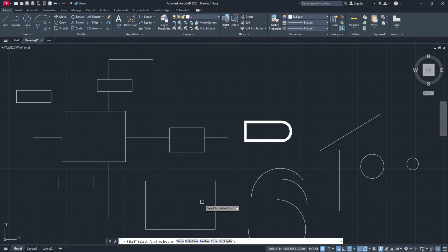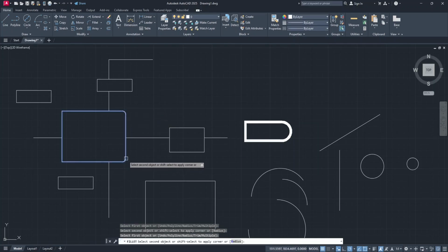As you've noticed, I keep coming back and selecting fillet multiple times, so you can select this multiple option to do more fillets in one command. So I select multiple, then select radius and give a radius of 30, and then press enter. I can select two intersecting lines to apply a nice curve at the intersection, just as here and here, here and here as well. And I can change the radius to an even bigger value, like 70, and then press enter.